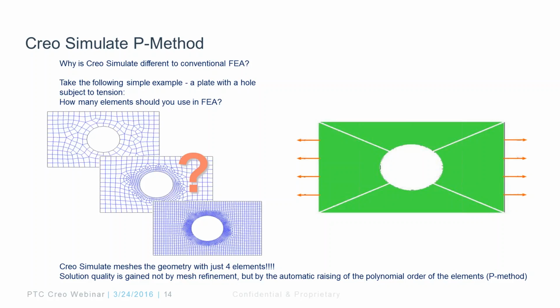Now, this is huge, right? So if I have a plate with a hole, do I just go with 1,000 elements, mesh tetrahedrons, or shells? Or do I go with 100,000 of them? How do I determine that? That's something that comes with experience in the traditional FEA tool.